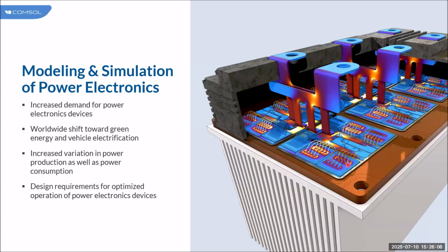That is one aspect. Another aspect is that you are seeing a power module here, and in this power module, once current is flowing and we have bus bars all along, because of the current you will have Joule heating, and heat will be generated. We can use the multiphysics aspect of COMSOL to evaluate where we are going to have hotspots generated due to temperature, and what the effect of current density is on that, in a simultaneous manner.